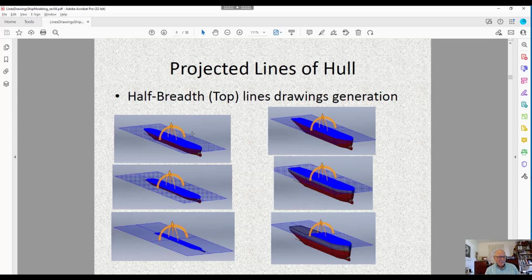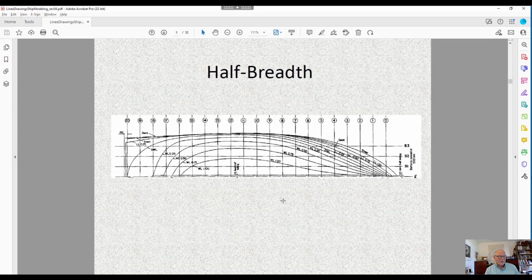So now the top is a similar kind of thing. Again, this goes back to that first ship. If you start slicing it and going up, as you go up, the outline changes and gets larger and larger. Looking straight down at it, this is the equivalent of doing that on a different vessel. And these, again, are matching up with water lines and matching up with stations. And from the top, you get the same increments as you do from the shear plan or the body plan, so that you can generate what's known as a table of offsets.